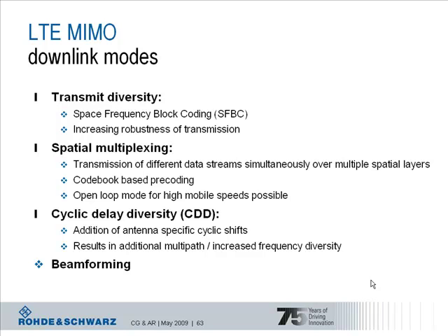An additional scheme used in LTE is called cyclic delay diversity. It is used in addition to spatial multiplexing as a further enhancement. An antenna-specific delay is added to the signal transmitted by each antenna, delaying the signal effectively, and this is done by a cyclic shift of the signal on each antenna. This effectively results in an artificial multipath situation experienced at the receiver side, causing increased frequency diversity effect. Finally, beamforming can also be applied in LTE as well, which is especially relevant for the TD-LTE part.